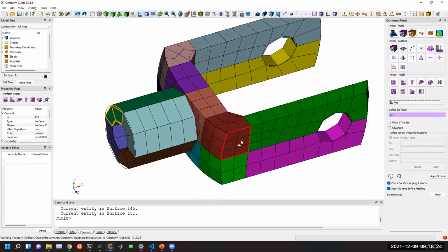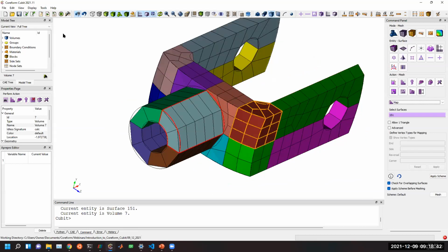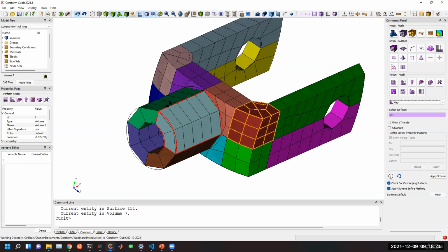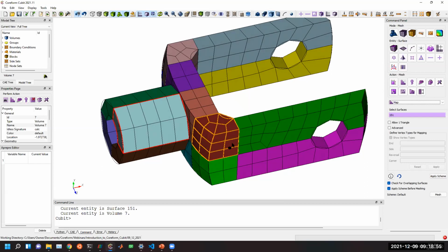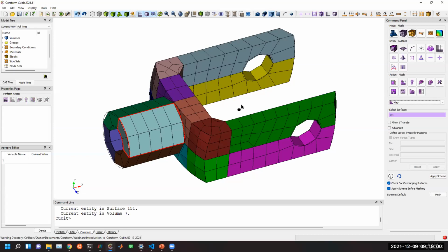I will say one limitation also in this version of Cubit is that between each of these volume boundaries, they are only continuous, not smooth. And that might be a reason why you may not want to do all of this partitioning in this current release of Cubit, because it does introduce decreases in continuity that you may not want. So that's a reason not to web cut as much. It's an implementation detail that we're also working to mitigate.